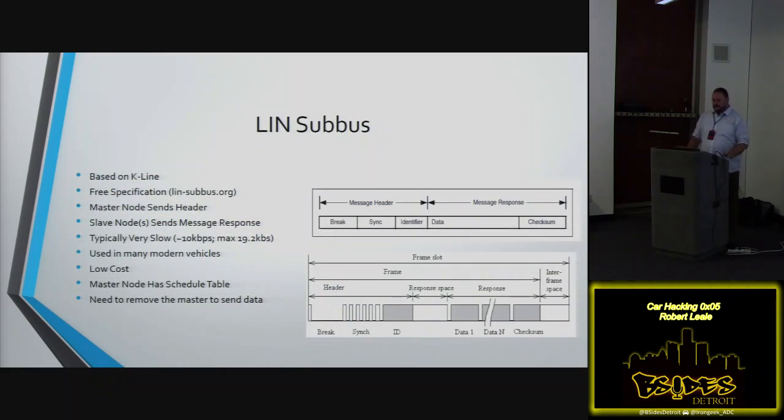So a little bit more technical. There's LIN bus as well. So if anybody here is familiar with CAN bus, which I'll talk about later, there's also another network that I like to use. It's very hackable. It's a lot of fun, and a lot of the new vehicles, their starting systems use LIN bus, and a lot of their lighting controls and things like that. Usually LIN bus is not broken out to that OBDII connector, but it might be broken out to other connectors in the vehicle. So you can find this network as well.